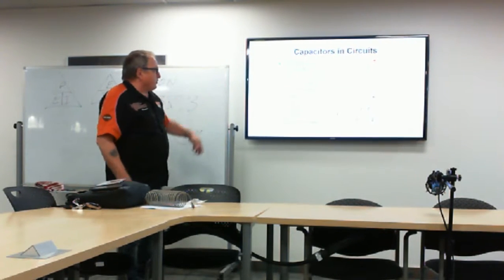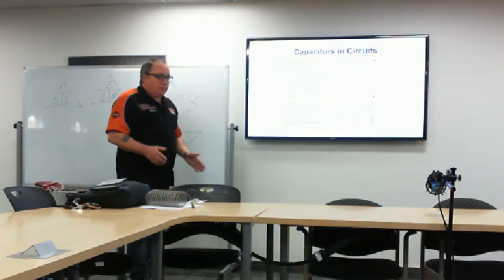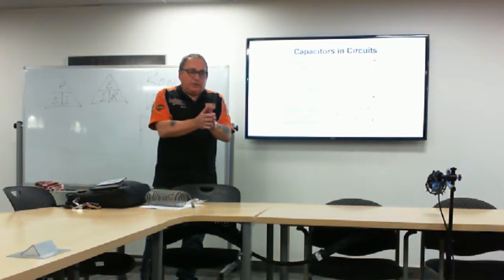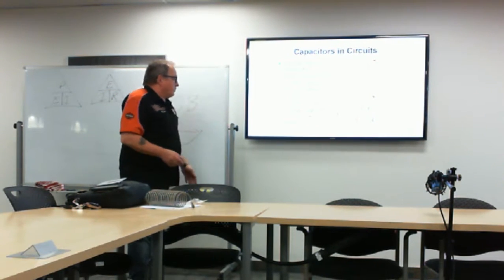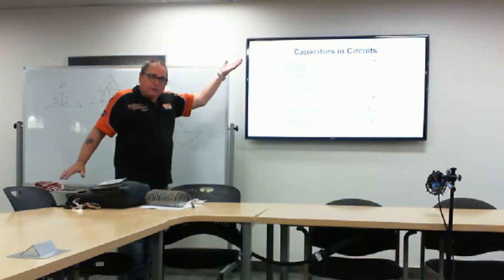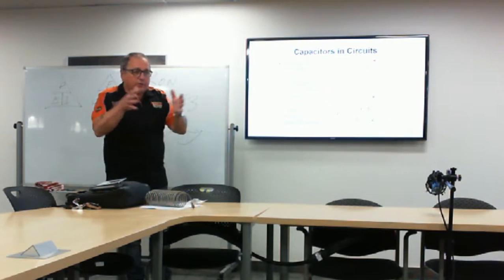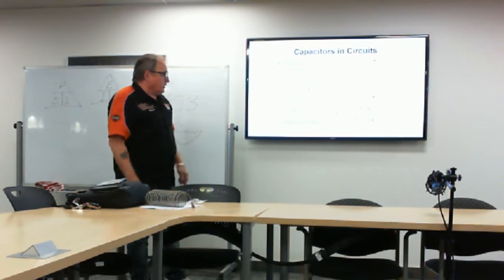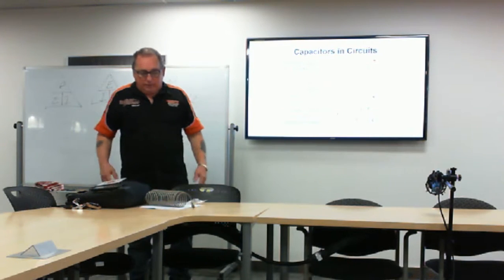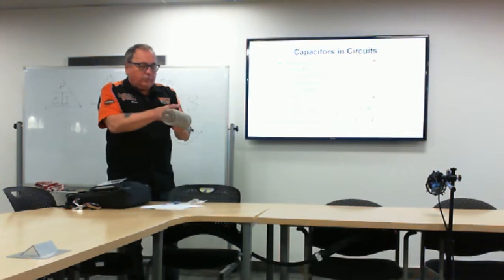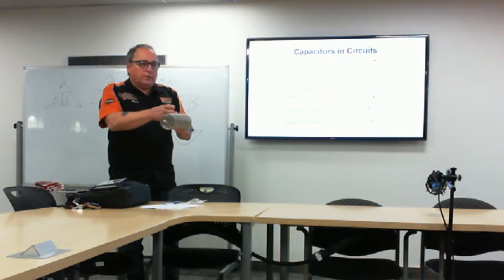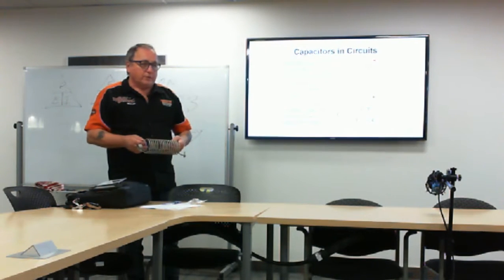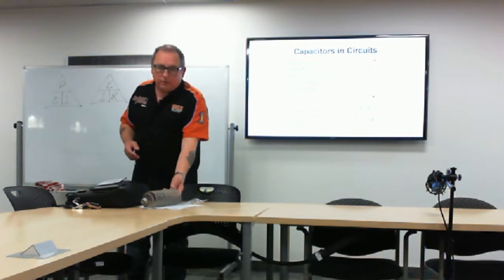Three physical factors affect capacitance values: plate spacing, how far apart the plates are; plate surface area, how big the plate is. That's why we roll up that tin foil, so you have some length like this in that little wee package. And the dielectric material, the thing that is between the plates. The dielectric is something that won't pass electricity, but it will pass magnetism.